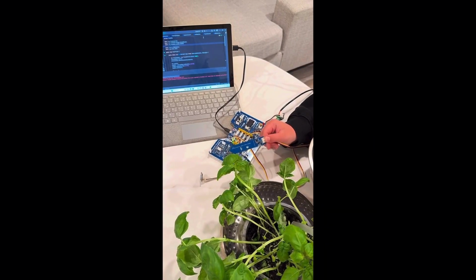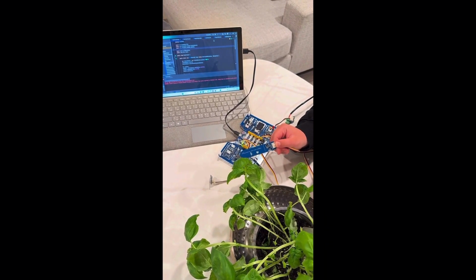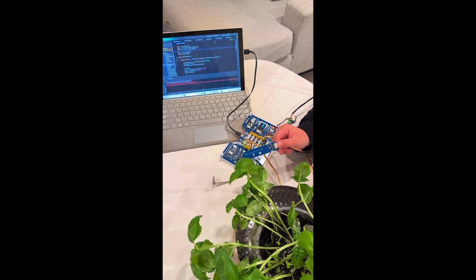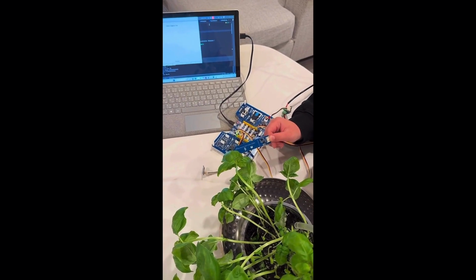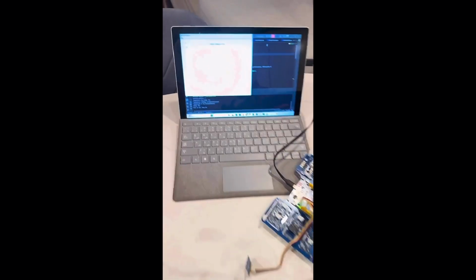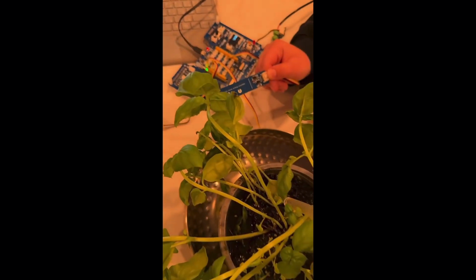Here the sensor is reading dry since it's exposed to air because my plant is currently wet, so the pump turns on. On the laptop, the graph updates with the new moisture voltage, and on the OLED, the system shows the current state and the reading.